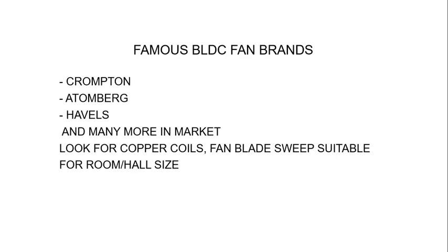So when you buy a BLDC fan, you have to look for copper coils, whether they use copper coils or aluminum coils. Fans with aluminum coils are slightly cheaper, but better go for copper coils. Then you have to see that the fan blade sweep is suitable for your room size or hall size.